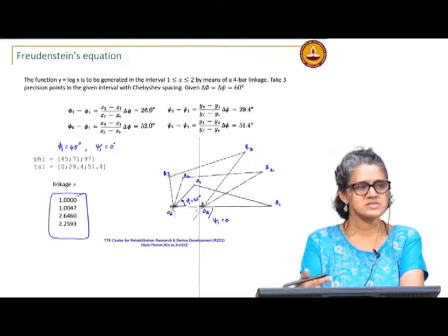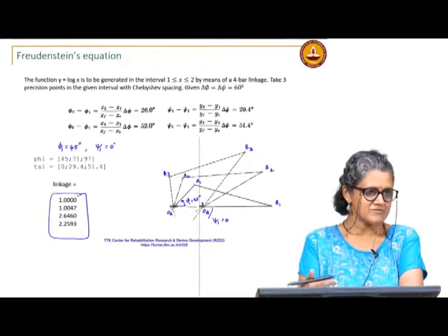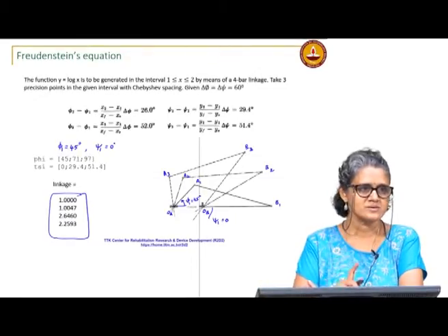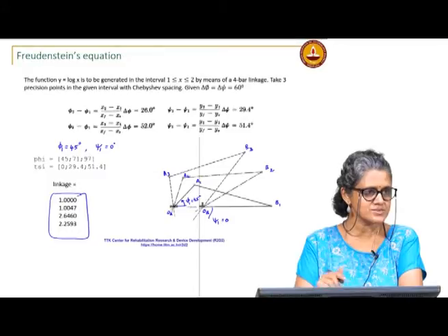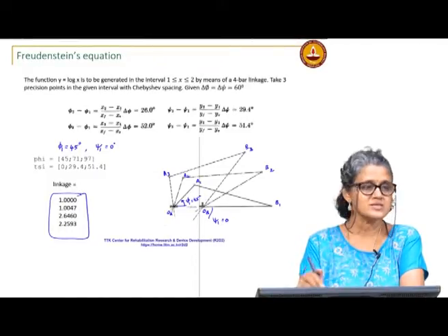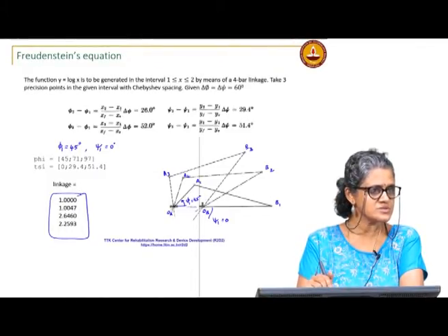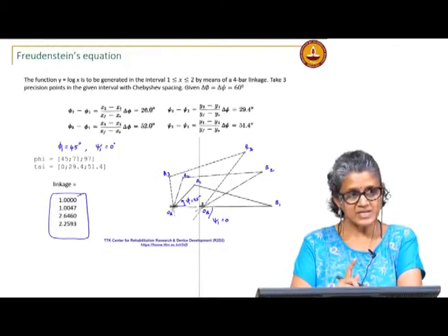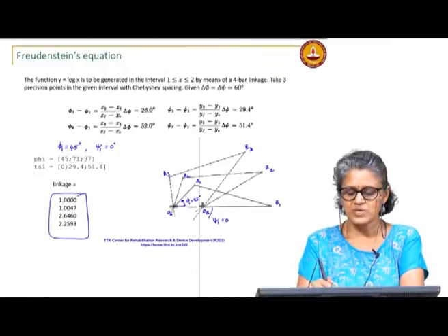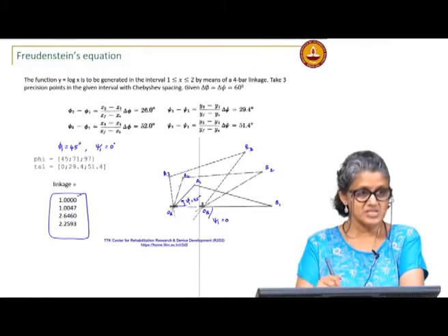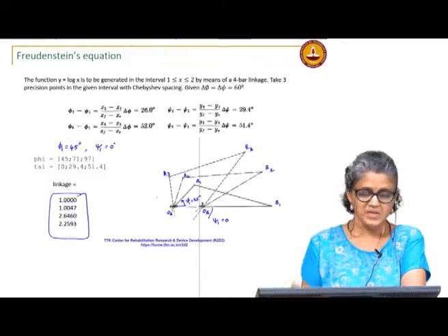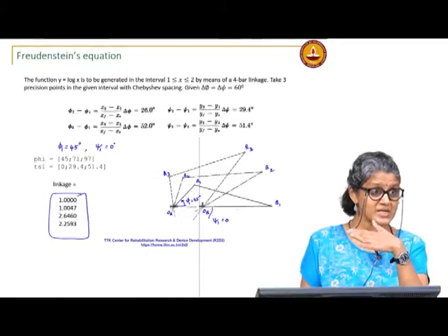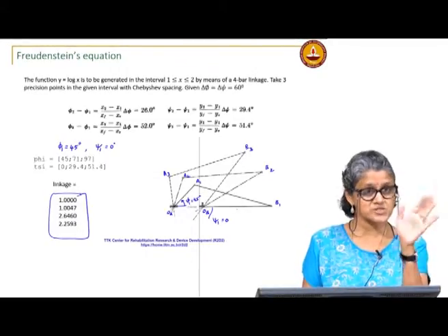I could have done this graphically also, but it is harder to do, to cycle through multiple solutions. Also, in the graphical case, if you noticed, once we specified one link length, especially for 3 position synthesis, I did not really have control over the initial orientation of the output link because of the method that I used.